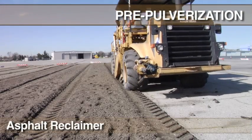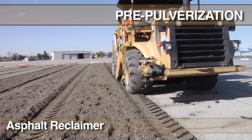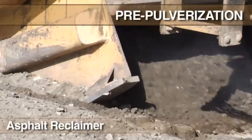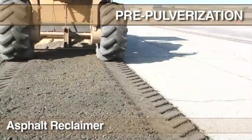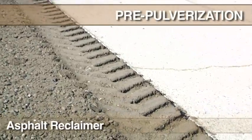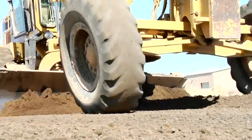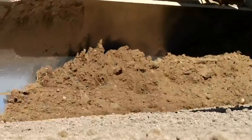Pre-pulverization is the process of grinding up the existing road and blending all materials in the design section. A reclaimer pulverizes the existing AC section into a uniform material with a top size of 2 inches. Pulverization is key to the FDR process and necessary for disrupting the crack patterns and sizing of the existing pavement materials. A motor grader shapes the road and prepares the road for the emulsion injection.